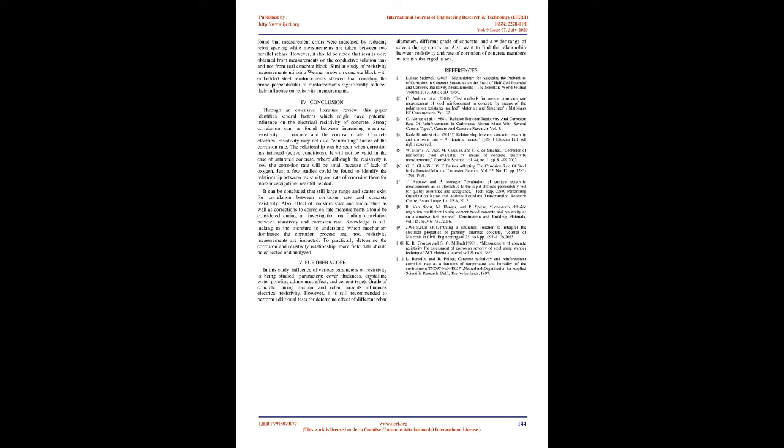Moreover, it was found that measurement errors were increased by reducing rebar spacing while measurements are taken between two parallel rebars. However, it should be noted that results were obtained from measurements on the conductive solution tank and not from a real concrete block. A similar study of resistivity measurements utilizing a Wenner probe on a concrete block with embedded steel reinforcements showed that orienting the probe perpendicular to reinforcements significantly reduced their influence on resistivity measurements.